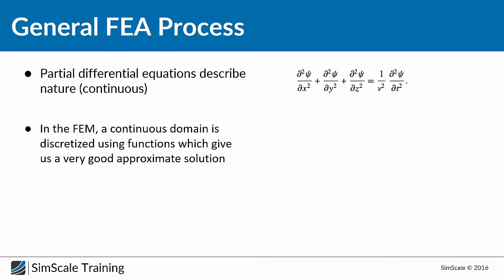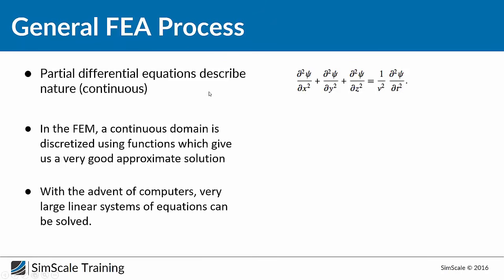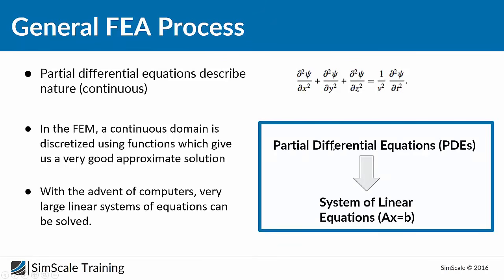And in the end, the idea of FEA is to solve a continuous equation which we cannot solve for a continuous domain by discretizing it using functions. And this discretization gives us a very good approximate solution. And that's in the end how FEA works. Basically, we are taking partial differential equations, PDEs, which we cannot solve, and transforming them into a system of linear equations which we can solve.